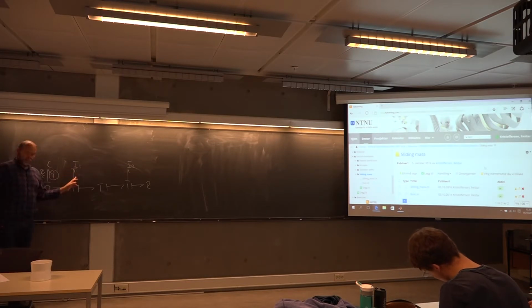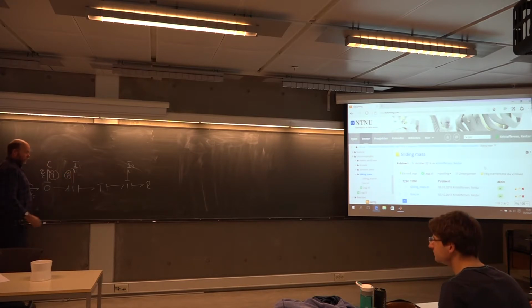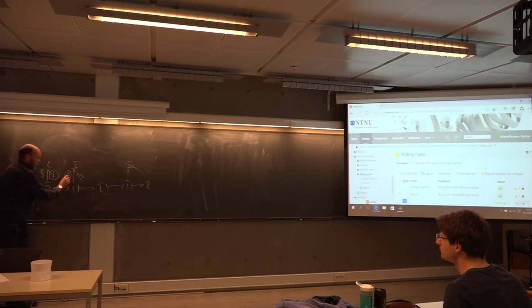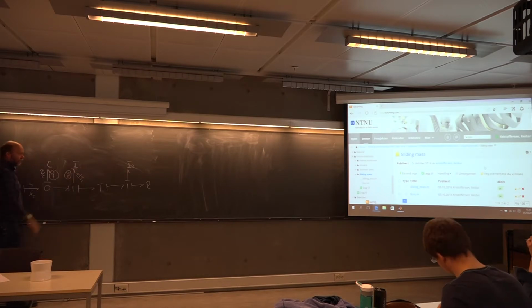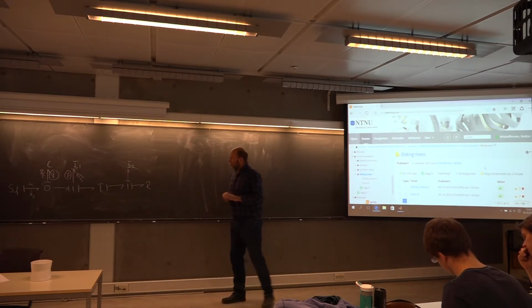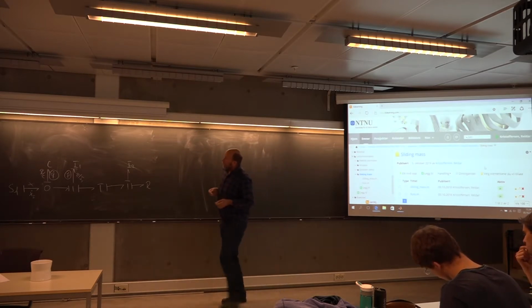The first mass is on the integral form, so here I will have an equation p dot, and on the other side p divided by I, and here I have to be careful, I1. You could have used p1 dot as well, since you have 2 masses, just indicating this is the momentum for the first mass, not the second, so you don't get confused. But this is as far as you go with the things that are given directly. So now we have to start nesting, finding the rest of the efforts and flows.